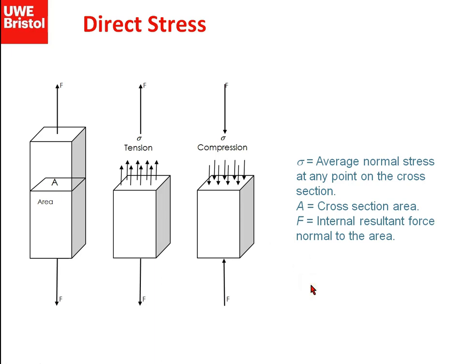So you can define stress therefore in two ways. You could define stress in what's called true stress, where we're measuring the actual area that we can see inside our component that we're trying to pull apart, and we're taking into account the fact that the area has changed. And then there's the engineering stress, where we take the original area of our member. But we don't need to go into those details.